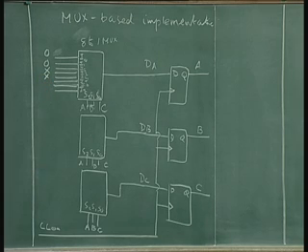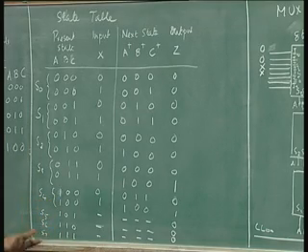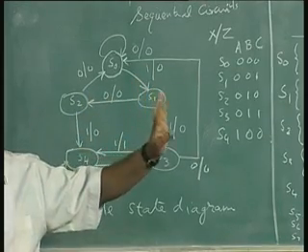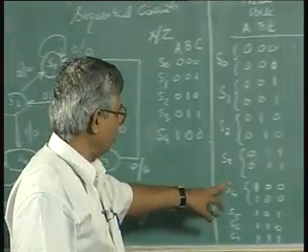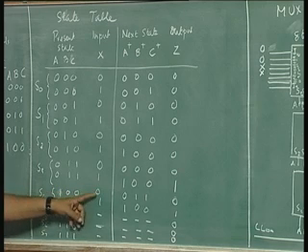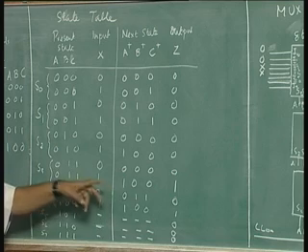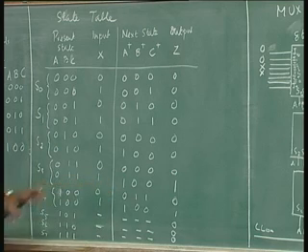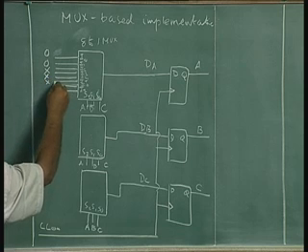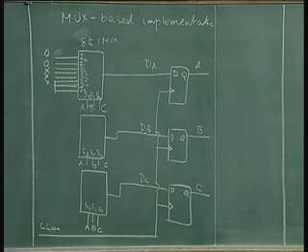S4, present state is 1. I don't know why, I just arbitrarily took this example. I just drew a map and it so happens that S3 again, S4 again the same thing. Circuit is in state 1, 0, 0. If X is 0, the next state is 0 for A. X is 1, next state is 1. So, it is again X. So, first 2 zeros, next 3 X's, and these 3 are don't cares.